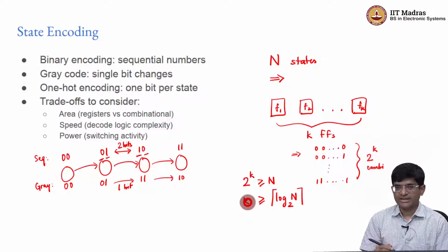Now, the interesting thing is, how do we do this as designers, right? And the point is that you have probably come across ways by which the state assignments can be optimized, right? In practice, when you are actually writing finite state machines for implementation in Verilog, you leave that to the synthesis tool, right? The tools are extremely good at exploring different kinds of FSM state assignments, and even if you just give some arbitrary assignment, almost certainly it's going to get re-encoded by the synthesis tool.